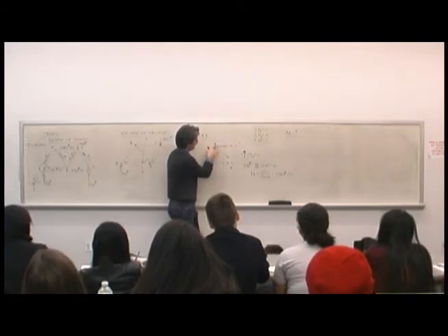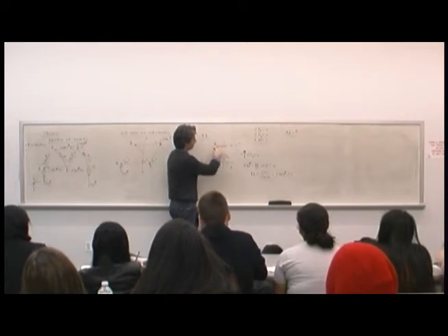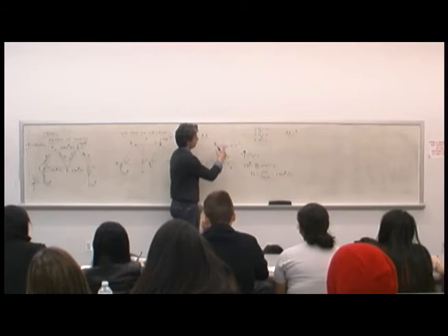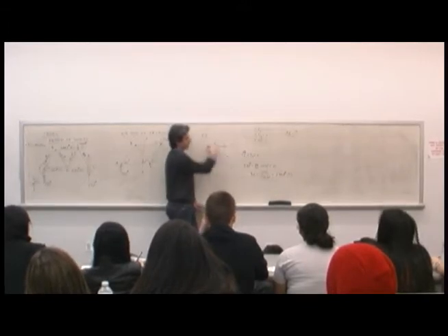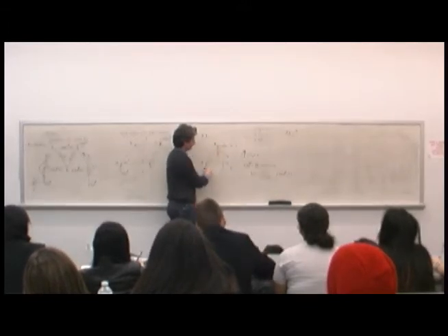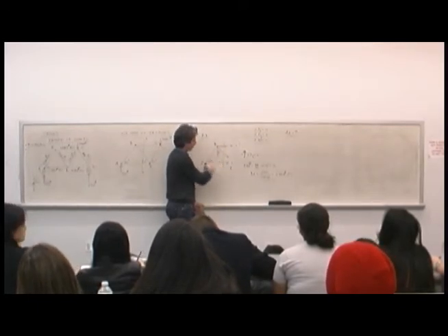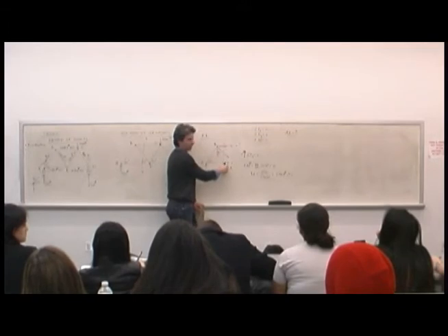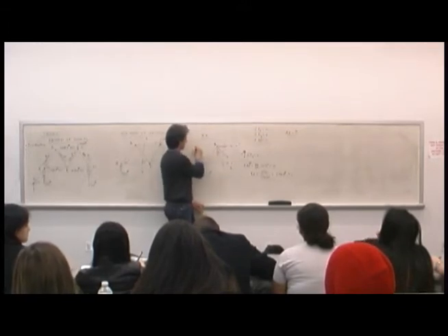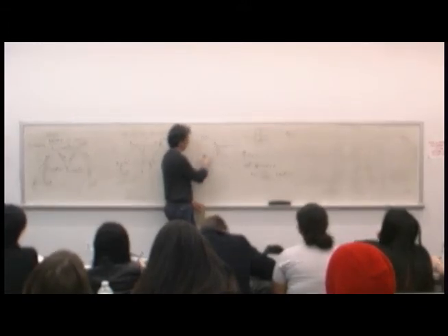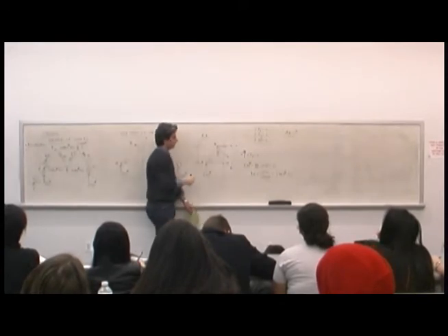Why B? I put myself at B, this vector goes away, this vector goes away, because it goes through me. And why does it go away? Because the moment arm is 0. So I don't have a moment around B. So then I'm faced with just this force and this force. So with two forces and a distance, I can figure out what AE is. But I need this distance. What is that distance based on this triangle?